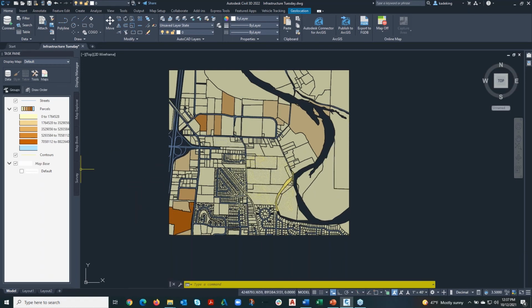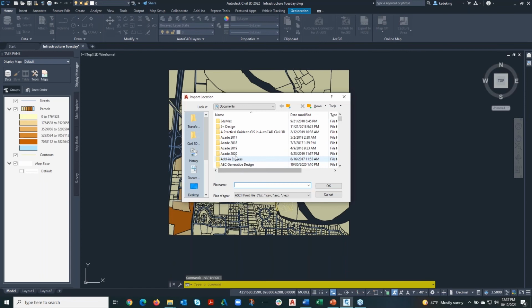So the next thing that I want to talk about for a minute, and I got distracted with the question, is that if you have GIS data that isn't in your coordinate system and you want to convert that and actually make a CAD file, if you simply have the current file with the coordinate system assigned to it, of course, it's going to automatically translate it. But that map import tool also has the ability to work with the current coordinate system and the other data.